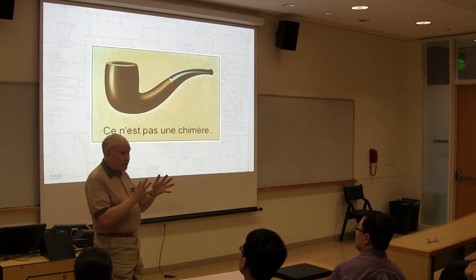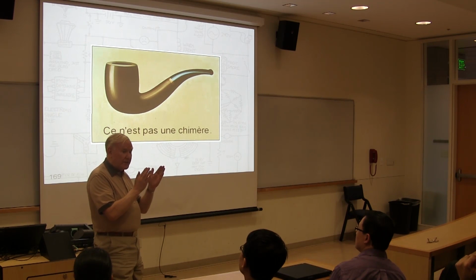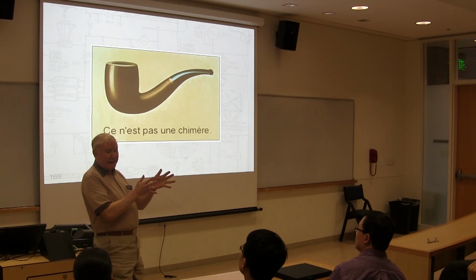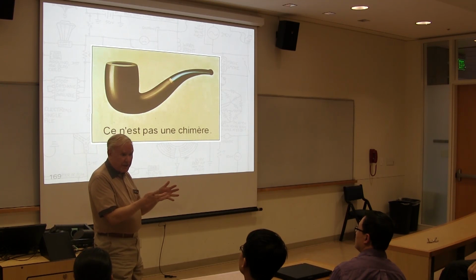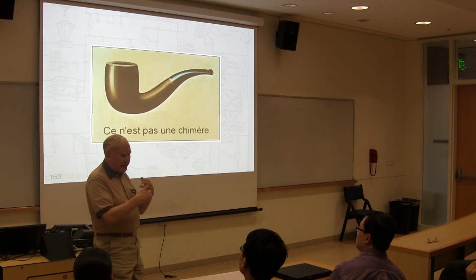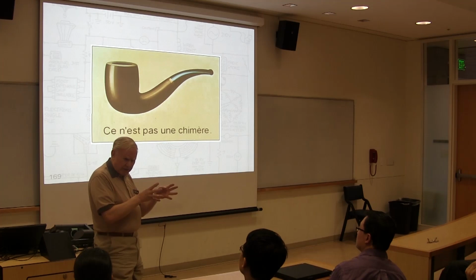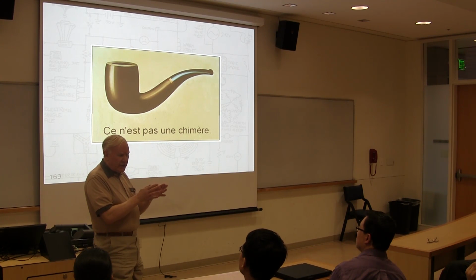But our focus has been to make the analog part as accurate as anybody can by the use of precision resistor techniques. I mean, thin film resistors are very precise, laser trimming to add precision, certain layout techniques to improve accuracy and so on. So we've been focused on that, and we're bound to be a little bit analog-centric because of it.